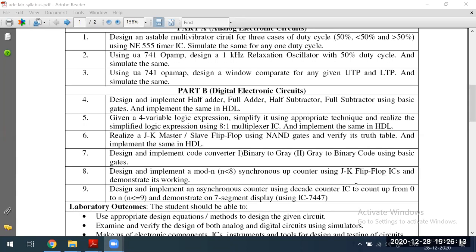With our normal eye, you cannot visualize or find out the difference between 10 hertz or 100 hertz or anything. You can only identify a 1 hertz clock. In 1 second, if it changes its state from 0 to 1, that you can identify. Any other clock you cannot visualize. If you connect an LED and see the output, it will always glow; you cannot see it turning off. You cannot differentiate. That is the difference. Now I think you have understood the meaning of the word clock input.